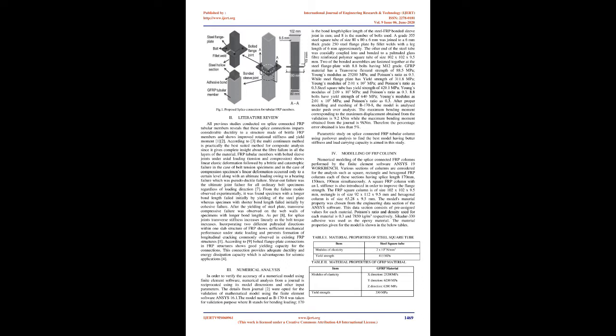All previous studies conducted on splice-connected FRP tubular members reveal that these splice connections impart considerable ductility to a structure made of brittle FRP members and show improved rotational stiffness and yield moment. According to [3], the multi-continuum method is practically the best suited method for composite analysis, since it gives complete insight about the fiber failure in all the layers of the material.